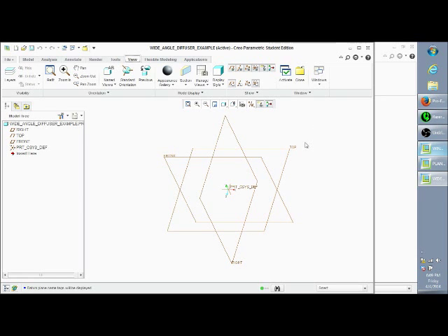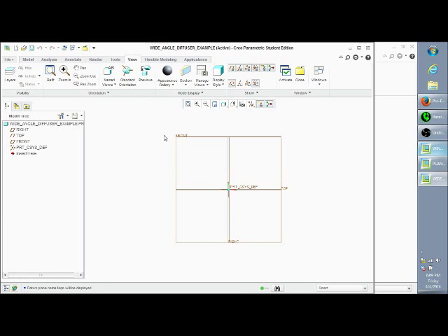So what we're going to do is start making the first shape. What we want to do is line it up so that we can start sketching. So go over here, under the View tab, Named Views, and we want to select Front. Now we're going to start sketching our protrusion, our blend.